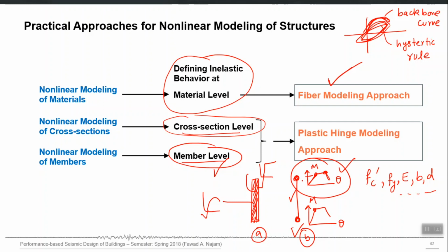Now this curve we just take and give it to the program as an input to that plastic hinge. So now the program has everything, it has the complete capacity of your beam or column. So demand it will calculate from the applied loading, and capacity you provide. Now it has everything to compare. Demand and capacity are compared, and the performance can be directly given at the end of the analysis by that program, right? So this is a quick overview.